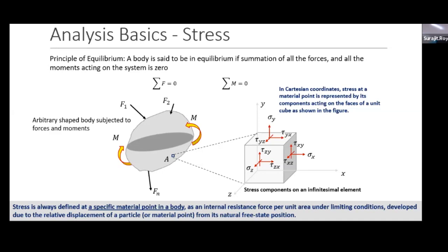The more confident you are about your design, the more the factor of safety is brought towards 1. It will never be 1, because you will never be 100% sure whether it is going to work or not. But the lower the factor of safety, the more confident you are that the design is going to work. The higher it is, the less confident you are about what type of loads are coming into the system, what type of failure is going to take place, and so on. That is what we talk about with factor of safety. Does it make sense, guys? Yes. It's basically nothing but a measure of our ignorance.